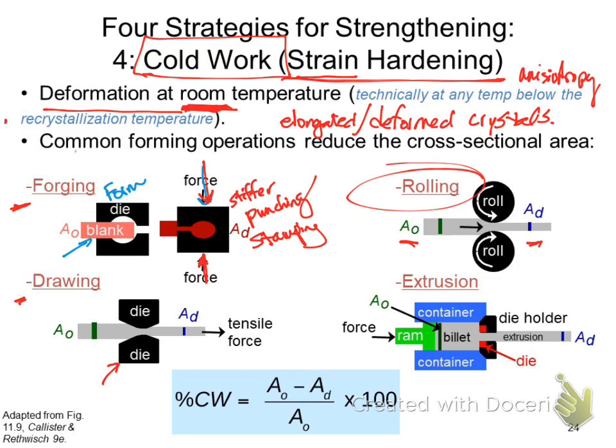You actually pull the plate through to achieve the final thickness desired. Okay, that would be not quite the same as extrusion, where you're still at this, remember, this is not necessarily at hot temperatures. You're not looking at molten metal here, but you have a billet of metal and you're actually pushing on it, pushing it through a die. So both drawing and extrusion use a die.